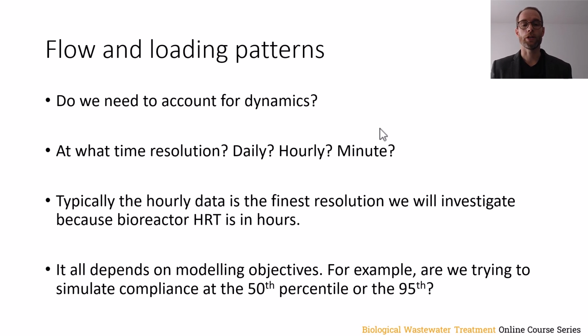For example, are we trying to simulate compliance in the effluent based on ammonia on a 50th percentile basis or a 95th percentile basis? If on a 50th percentile basis, maybe the steady state results are the most important ones. But if it's on a 95th percentile basis, that is to say we need to demonstrate compliance more than 95% of the time or 95% of the days in a year, in that case, maybe we need to be simulating the input dynamics on an hour-to-hour basis because we want to see all of those breakthrough peaks that we're expecting.